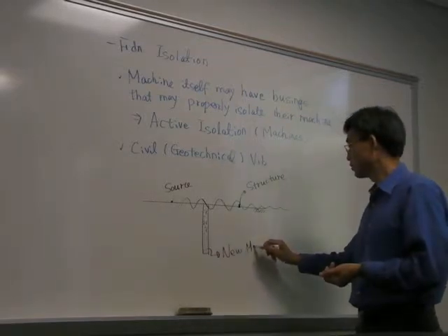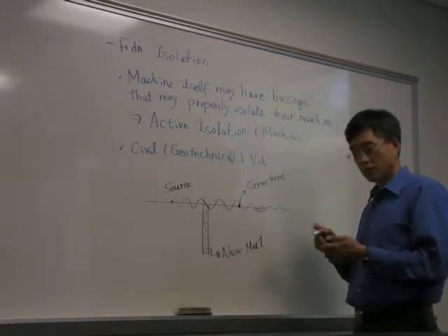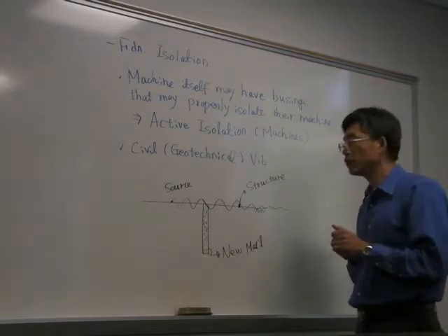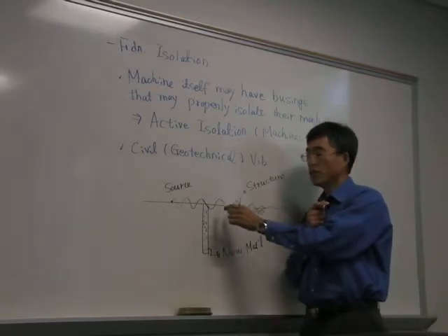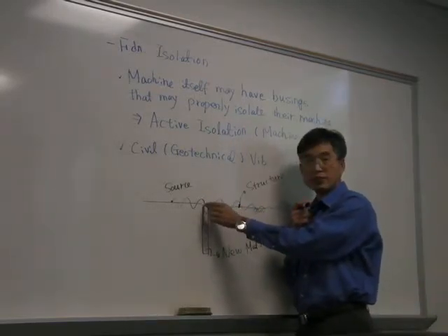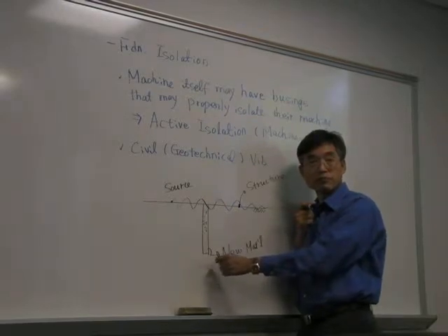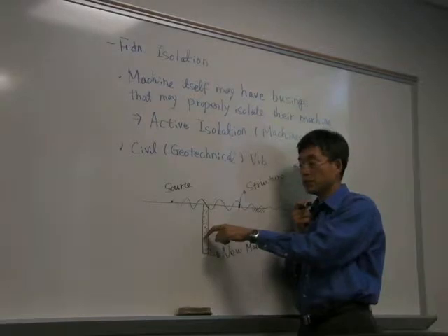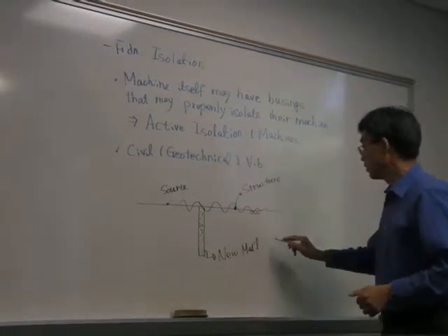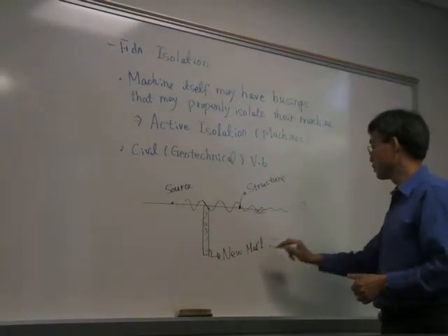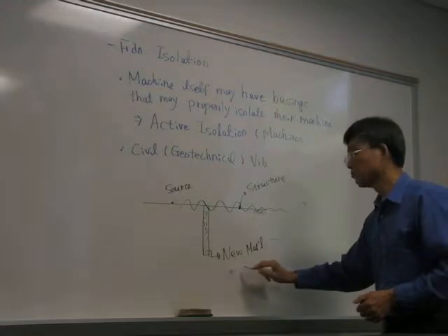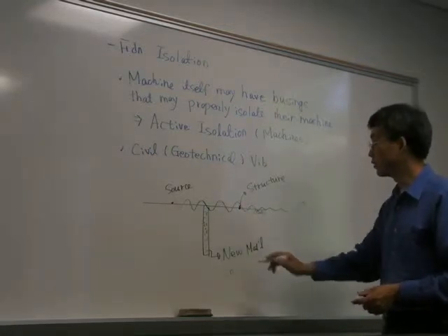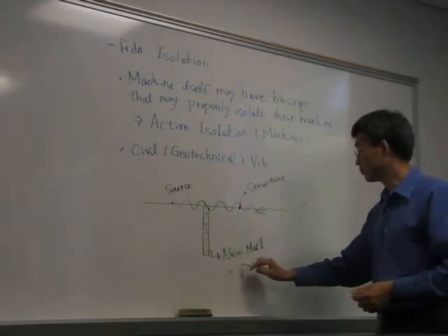So probably what we need to do is excavate a trench here and fill some kind of materials in the trench. And think about what kind of materials in this trench may be very effective to cut down the vibration.